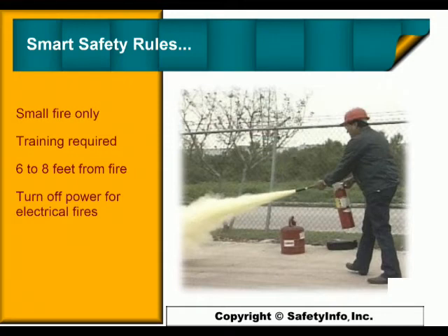Never place a pressurized fire extinguisher upright unless you are holding it. If it falls over, the nozzle can break off, causing an explosive release of the pressure in the extinguisher. For electrical fires, always turn off power before attempting to fight the fire. Never touch electrical equipment or boxes with any part of the extinguisher. A shock hazard may exist.